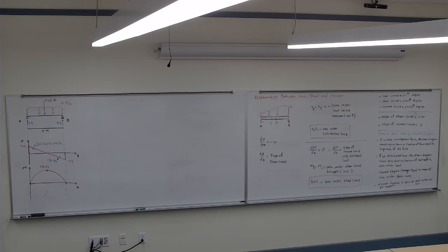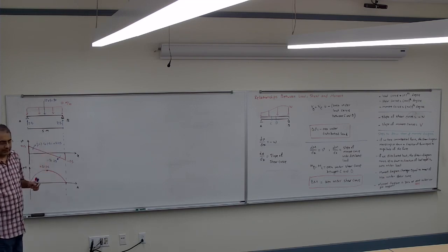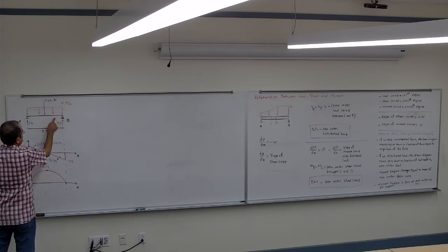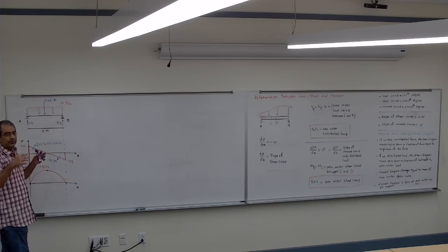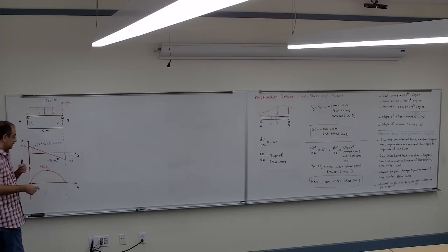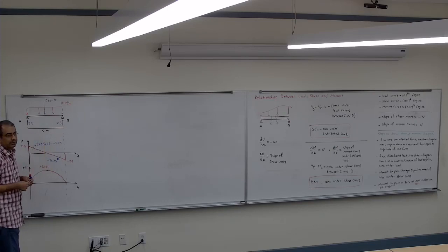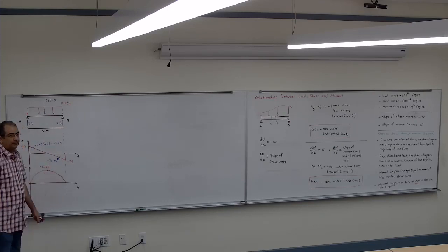So you mentioned that this doesn't completely work if there isn't a roller or pin at the end. What do we do in those situations? If it is not, I think we have an example I'll show you. Assume instead of this being here, it's there. Then I cannot just assume this is 0. So I don't know at the beginning that it's 0. So I have to add them and subtract them and see what I get when I get to that point. If it is at the end, I can right away put 0 there.